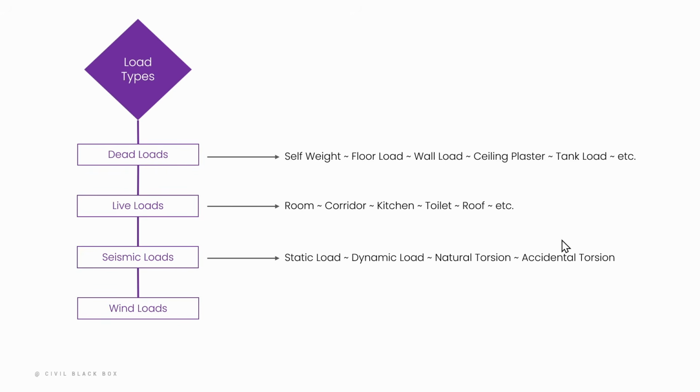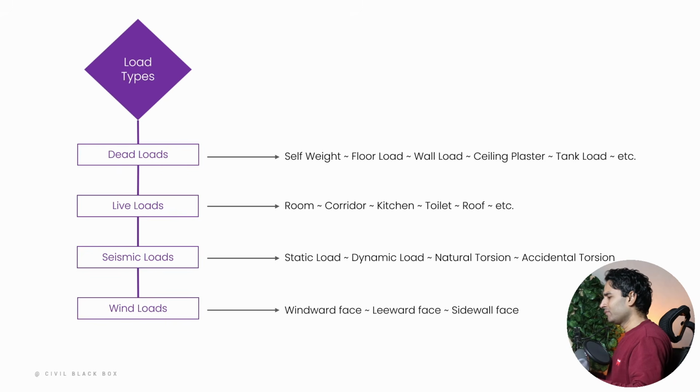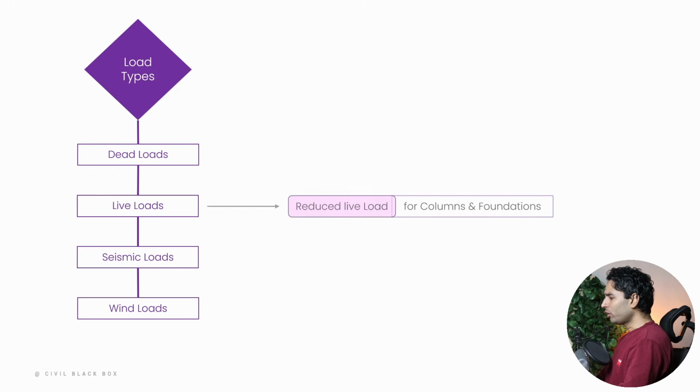Lastly, we have the wind load criteria, where we, in essence, talk about the wind load application on the windward face, the leeward face, the sidewall face, and so on. Moving on, we have one special criteria which comes for the live loads, which is a concept called reduced live loads. Now, this is particular for columns and foundations only.